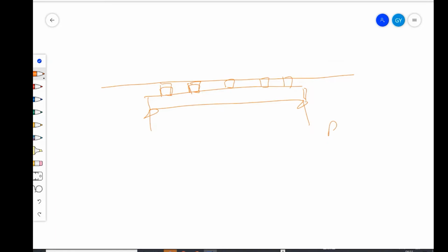We have the rail free fastenings. We call them rail free fastenings. Now what is the property of rail free fastening? The property of rail free fastening is, if this rail is trying to move in the longitudinal direction with respect to the sleeper, then these fastenings are not resisting that movement, right?